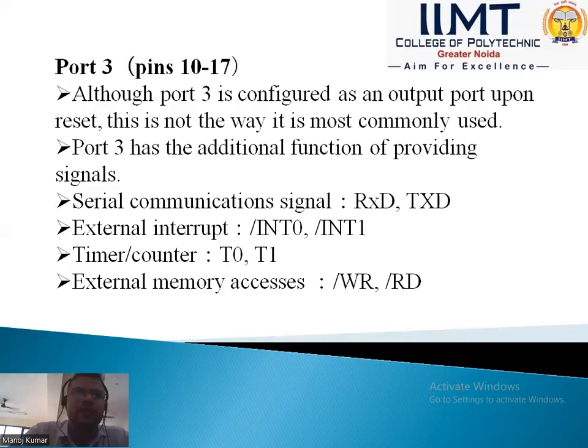used. Port 3 has the additional function of providing serial communication signals RXD, TXD, external interrupts INT0, INT1, timer counter signals T0, T1, and external memory access signals WR, RD. These are all timer and counter signals.